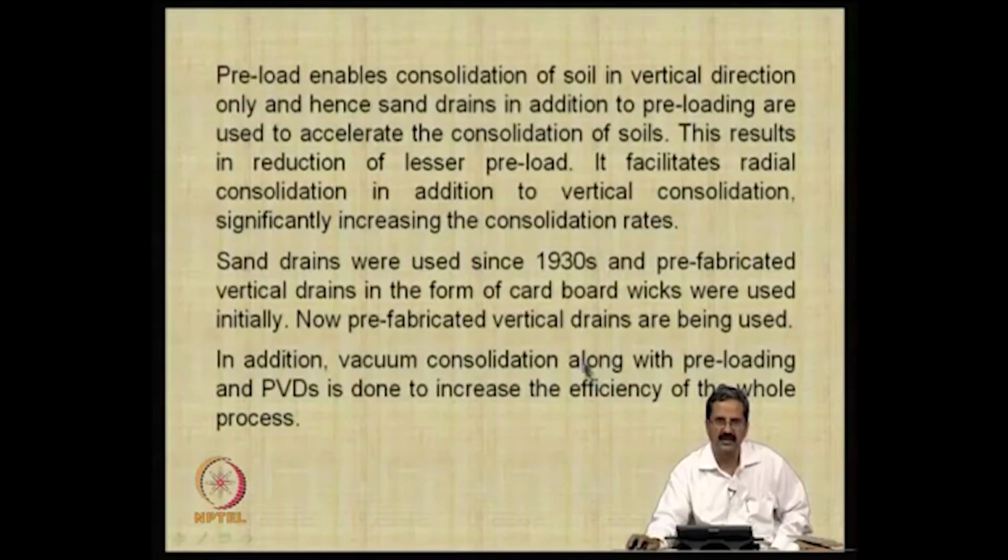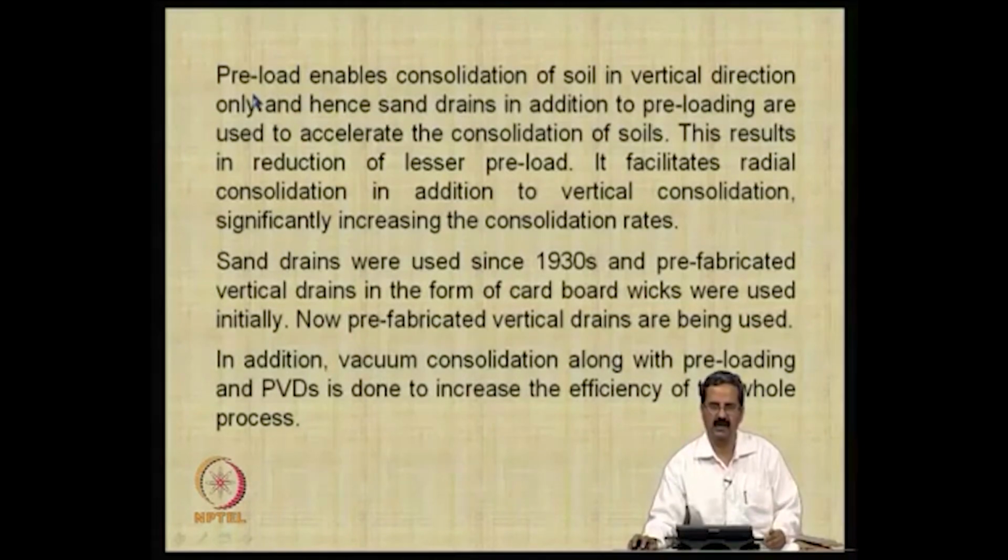In preloading, it is only the vertical consolidation of soil that is effective, but in the case of PVDs and sand drains, you have radial consolidation also, and it results in lesser preload.